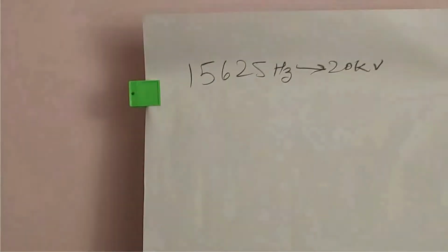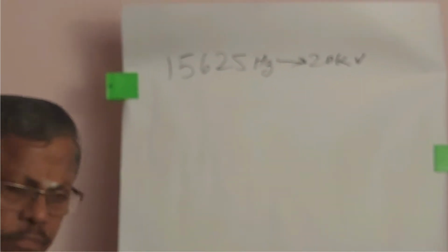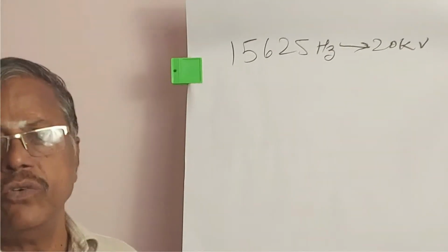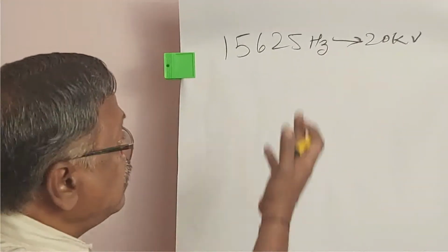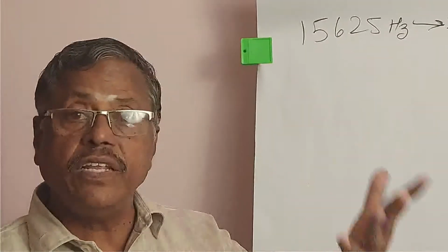That cannot be rectified with normal diodes. It cannot be rectified with a 1N4002 or any other diode like 1N4148. You cannot use them. Those diodes are not meant for that, not even a BY127. There have to be different diodes. The diode has to withstand this much voltage and also be a fast recovery diode because of the very high frequency.